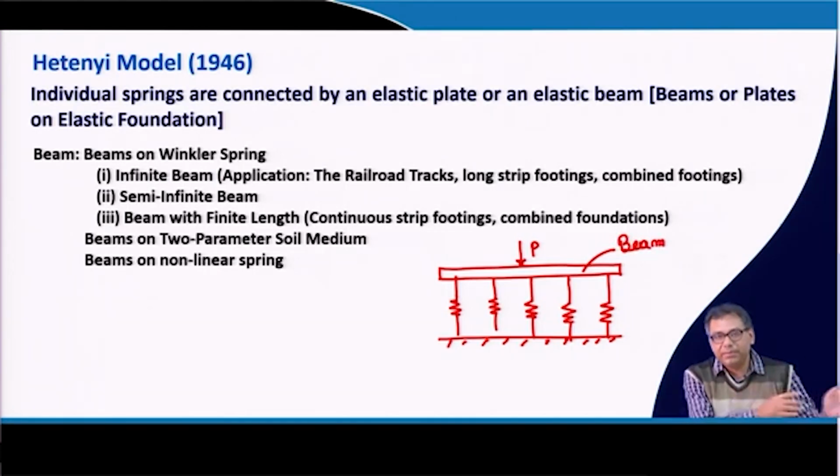Beam. So, now in the previous model the interaction between the foundation and soil was not considered, it is only the soil. But now in this case, if the foundation is idealized with a beam or plate, and the soil is idealized with these mechanical elements, that means either spring or spring dashpot, there is an interaction between this plate element or beam element with these mechanical elements. Okay, now here also the connectivity issues can be solved, and the settlement will not be confined within the loaded region.